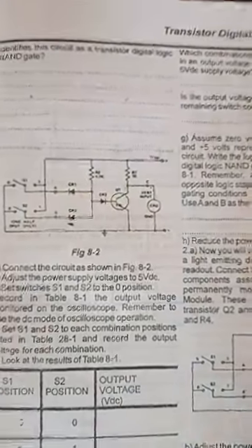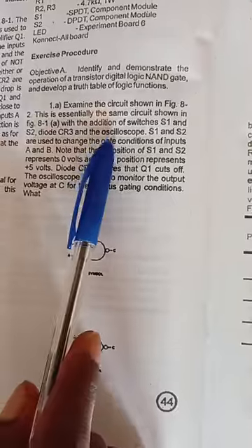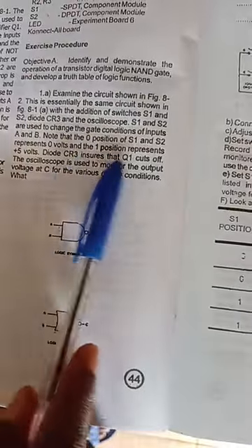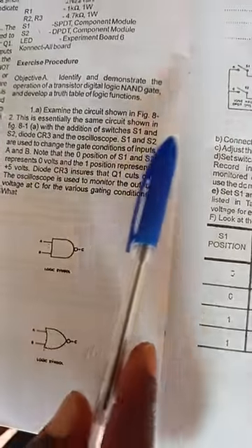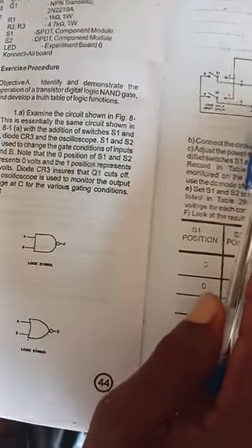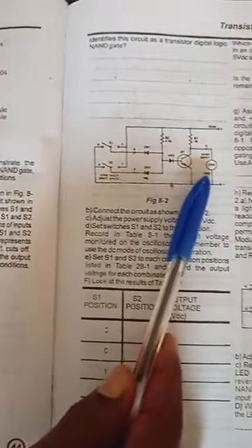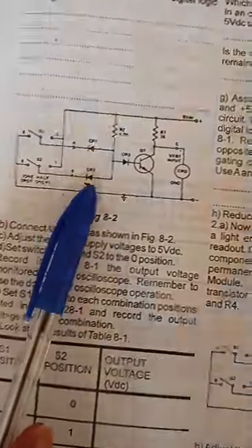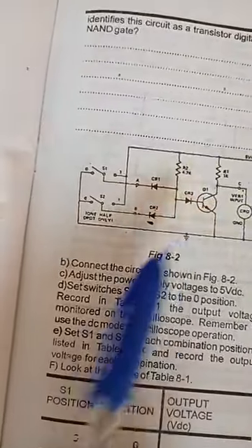So we are going to have two signals, and we are going to have our output from here, which is C. In this particular case, we have to use an oscilloscope to look at our output. Switch 1 and switch 2 are our input, and they will be in two conditions, either 0 or 1. In the AND gate, we use only 2 diodes. We're going to use 3 diodes in this one in order to reverse the condition of the AND gate to become a NAND gate. We use this third diode to reverse the outcome from these 2 diodes, which would give us the AND gate. We reverse it to give us the opposite value of the AND gate, to become the NAND gate.